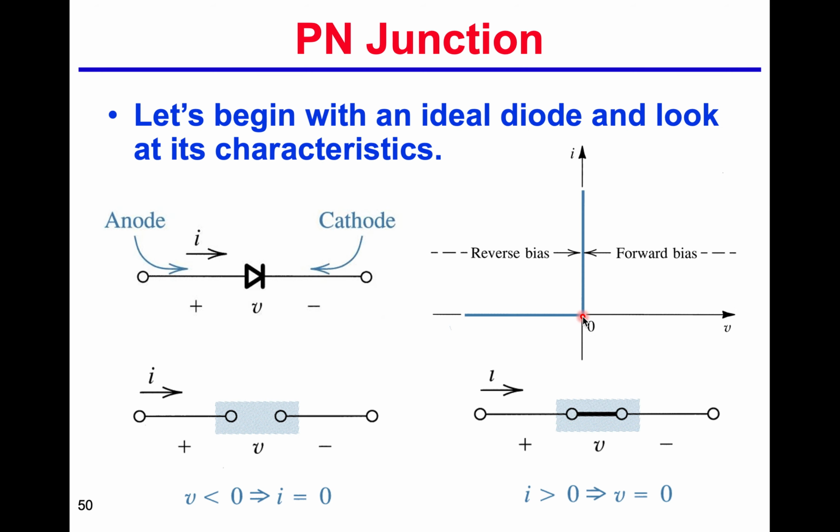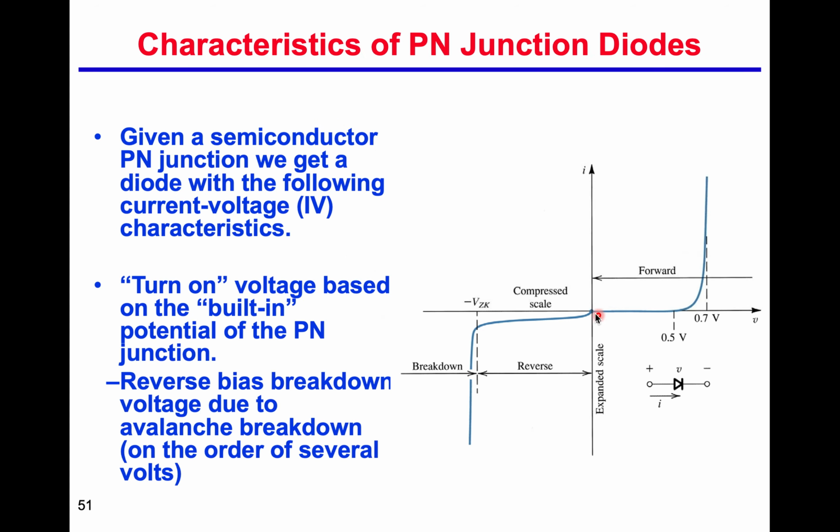So which means we need some turn on voltage. Here is, for example, maybe 0.7 volts we can turn on. And we will see that actually the turn on voltage depends on the material system. If that is a wider bandgap material, for example, the nitride system, then we need a larger turn on value. And if that is for the phosphide system, that will be shorter.